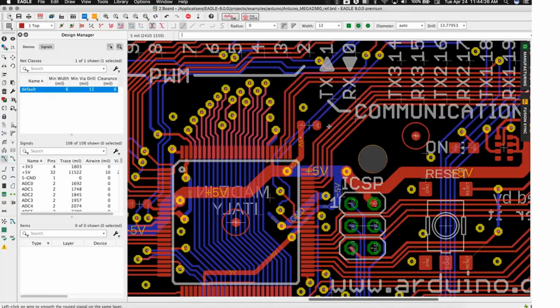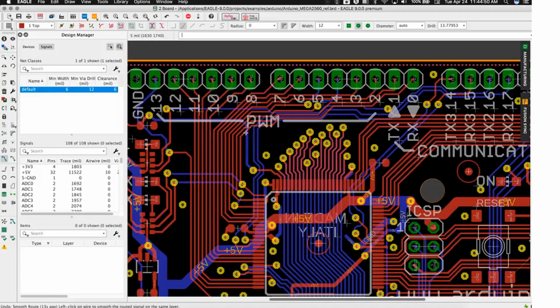So in this case, you saw that there was a whole variety of connections up here which had extra signal length. Aesthetically, you could argue, well, oh, but that bundle's closer to this, and so that kind of looks better. But the physics of it are actually not better. The physics are always better when we've got something which is a shorter track length. So in this case, the cleanup has the ability to shorten track segments, and we'll look to try to remove a lot of those additional jogs in a track segment. It'll also look at things like this, and you can see here how it straightens up those connections over there.